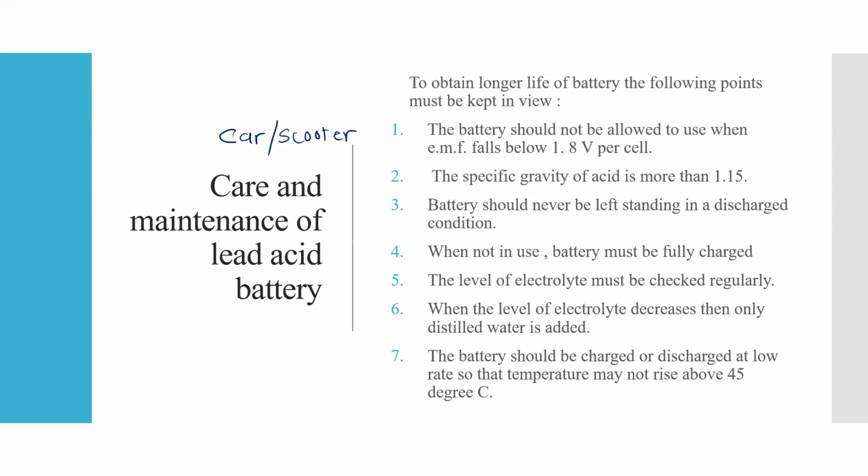we are not using the battery, particularly lead acid battery, then the battery must be fully charged. Remember. Okay, this is applicable to your car as well as scooter. If it is discharged and you just leave it for 10, 15, 20 days, and after 20 days you try to apply the ignition, you try to start your scooter, it will not start. Okay, so when it is not in use, then battery must be fully charged.